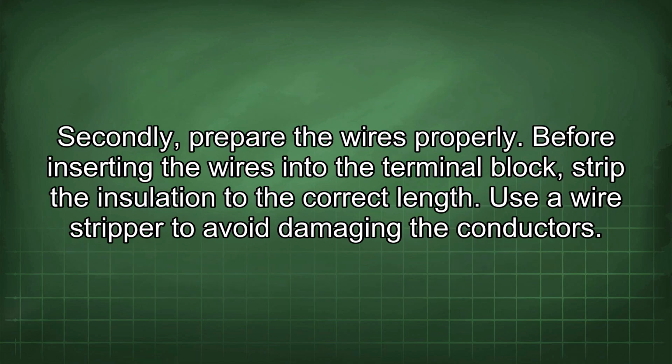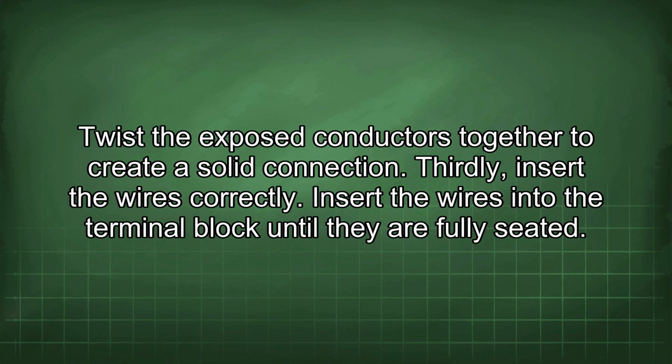Secondly, prepare the wires properly. Before inserting the wires into the terminal block, strip the insulation to the correct length. Use a wire stripper to avoid damaging the conductors. Twist the exposed conductors together to create a solid connection.